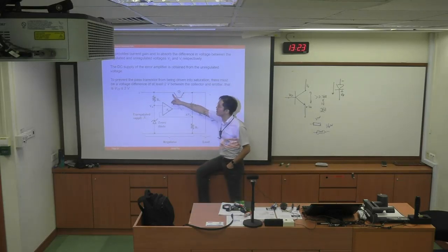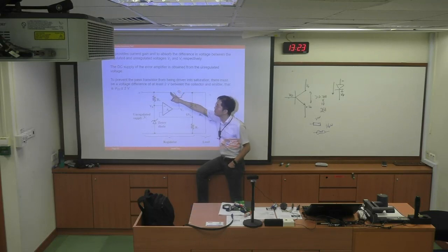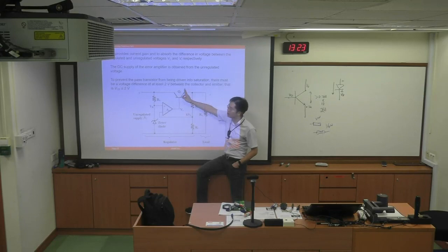And the reason is because NMOS always has a threshold drop, meaning that you cannot pass the same voltage from here to here in the full VDD, whereas a PFET can pass the full VDD to the other side. If you don't want any voltage drop more than what you want, you'd better use PNP transistors, PFET transistors.